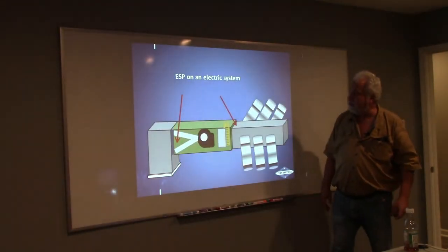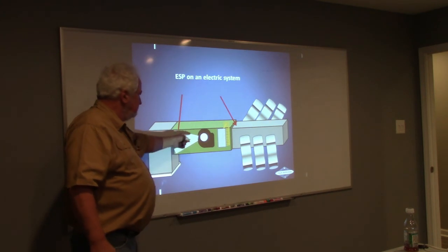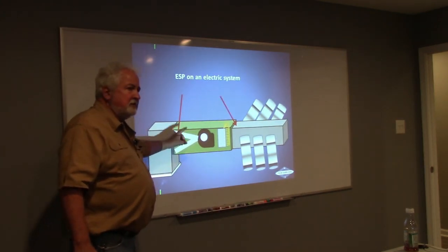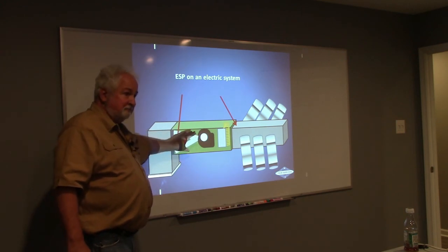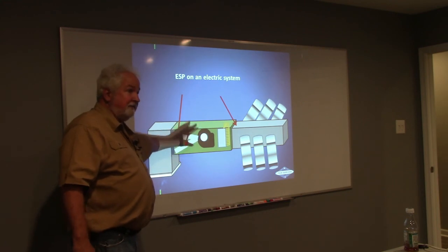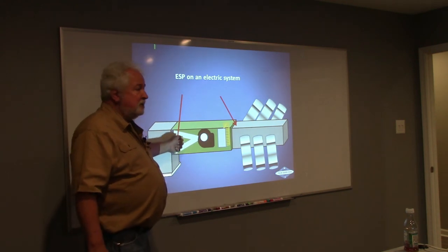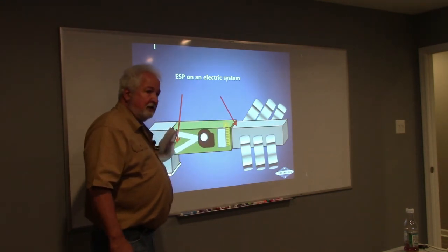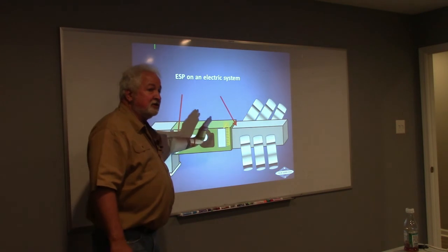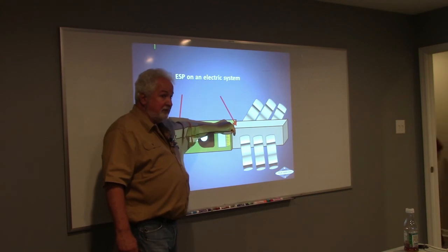Good. All right, so let's look at an electric heater. Where's the coil on an air handler? It's inside the air handler, yes? Does the guy at the factory that's putting in this blower know what kind of coil he's putting in this air handler? He knows. He's building this thing for that coil, so he knows the resistance on that coil already. So when I'm doing an air handler, I'm going to measure external to the cabinet of the air handler. But on that gas heater, I had to measure external to the gas heater, but I had to include the coil because they didn't know what coil that was. Does that make sense? Cool.